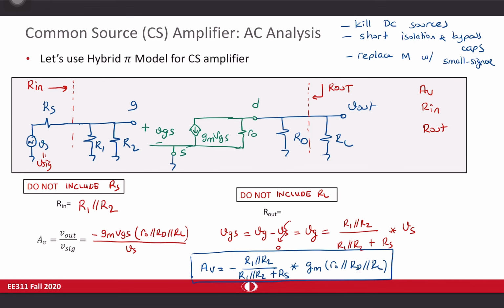So what does this mean? This means that input and output are in 180-degree phase shift. So this negative sign tells me that input and output have 180-degree phase shift. So if you apply some input signal with this phase, we have a signal like this. At the output, you will have the opposite one. So it introduces some phase shift.